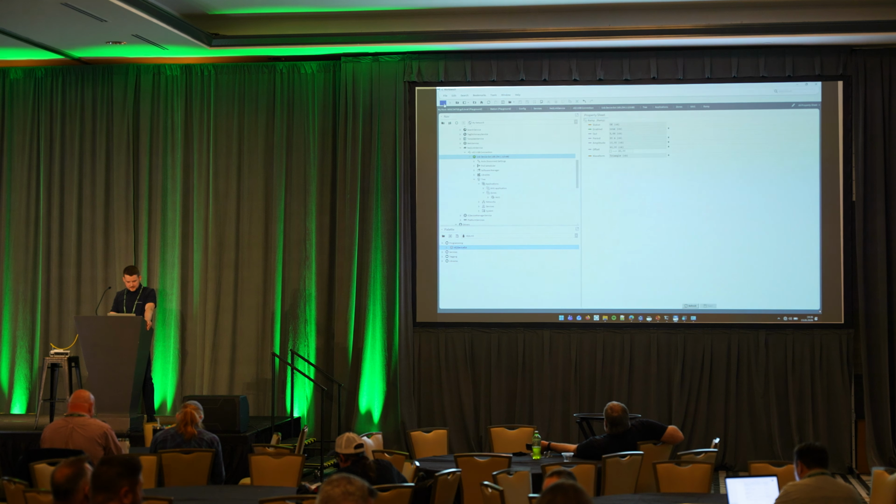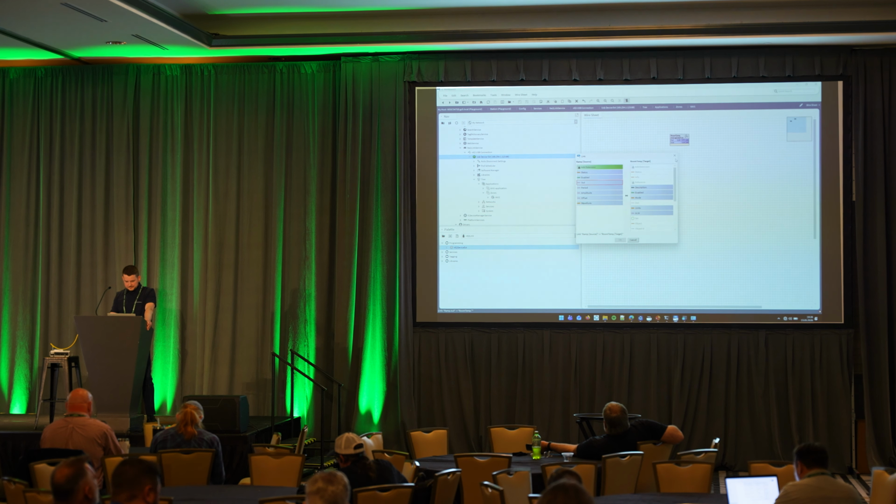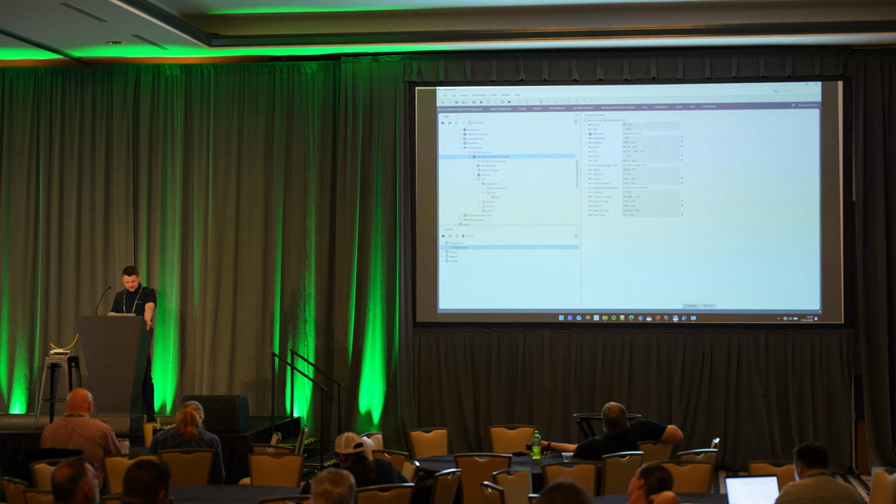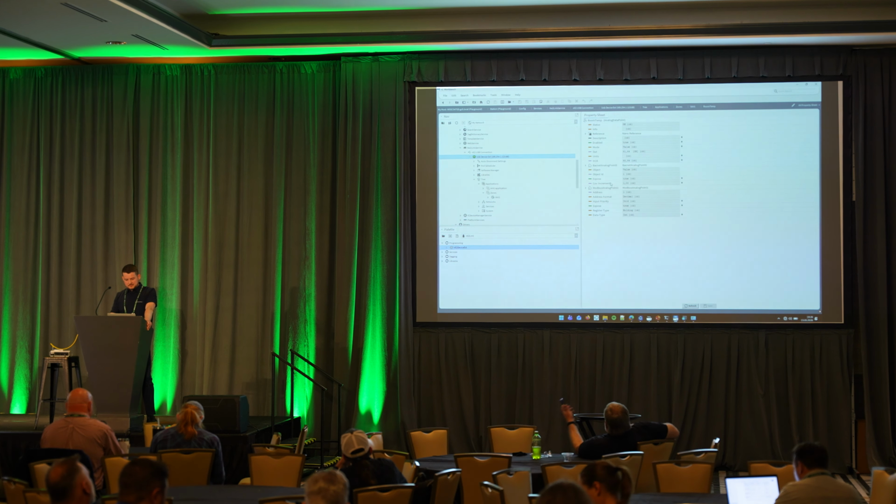Save it. Right now we can link it here to the point. So we build our first logic here inside our controller. We go to the room point. You can see that this point is now being natively exposed over BACnet and Modbus protocols. You can configure it the way you want, so you can disable either Modbus or BACnet if you don't use one of them. But by default, you have just all the data available on the network as you go.